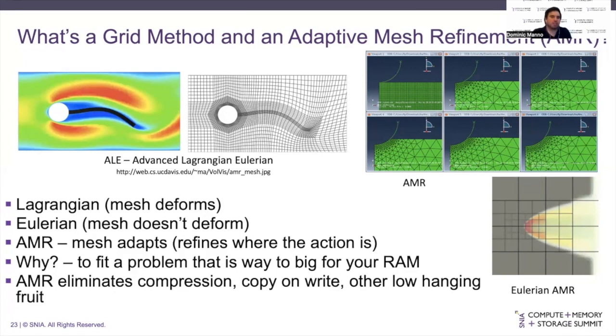And the simulation processes do the computation on that process's cells, obviously, every single time step. But then after a time step, boundary information about these state variables is exchanged with neighbors. And then the mesh will be rebalanced based on the interesting properties of the simulation. And that reorganizes the state and data based on refinements that are required for the mesh.